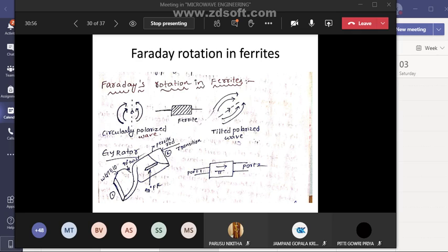The ferrite materials are oxide based components in the form of MnO and Fe2O3. The ferrite rods are obtained by firing powdered oxides of materials at 1100 degrees centigrade or more.